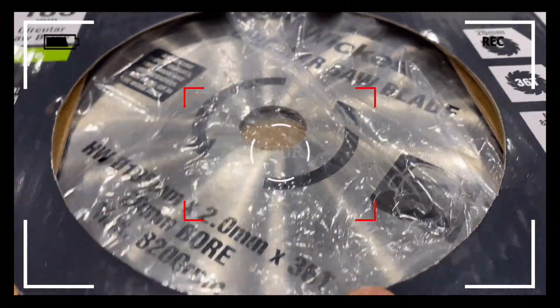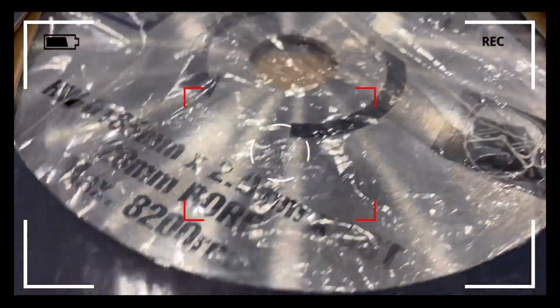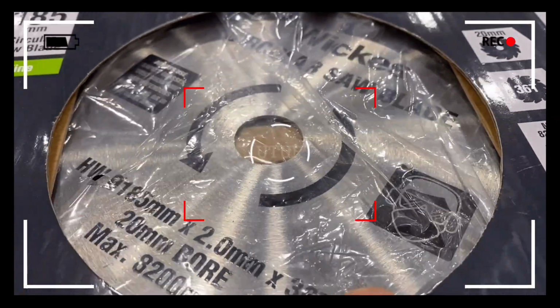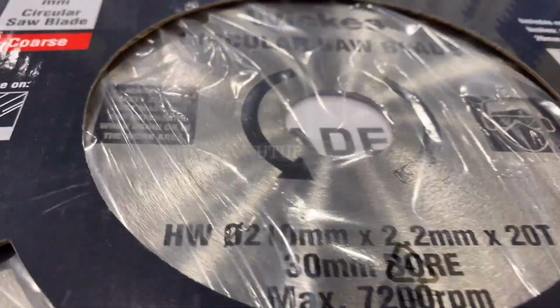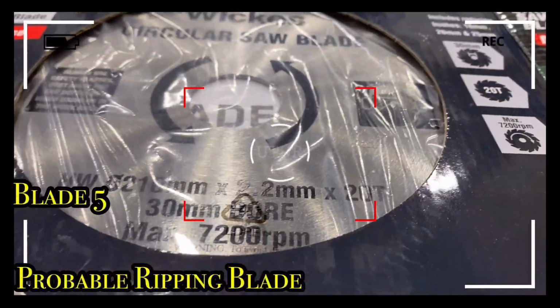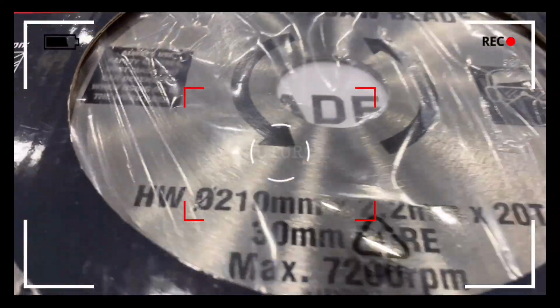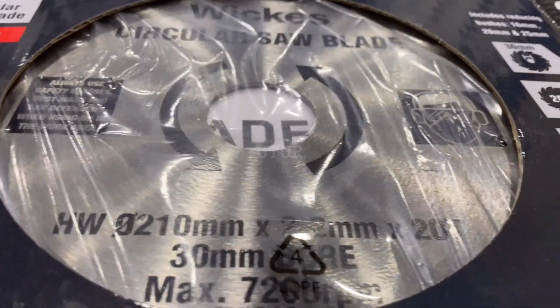The blade on the inside could be a ripping blade with more teeth and a smaller gullet. The next blade has got a 210mm or 8.25 inch rim size, a 2.2mm kerf, a 7200 RPM and a 30mm bore.